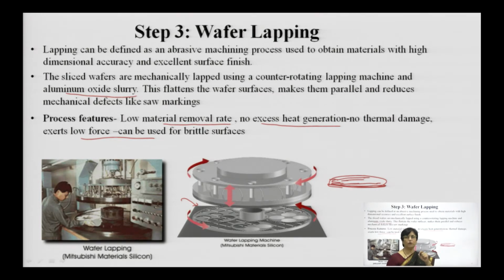So, this is the process which is called lapping. The abrasive materials can vary from polycrystalline diamond to silicon carbide, and multiple materials can be used for this process. This process is also exhaustively studied, and for different applications, if the material or wafer is very brittle, then you tend to use less abrasive material. In the case of silicon, you normally go for the aluminum oxide slurry, which is used as the material for lapping.